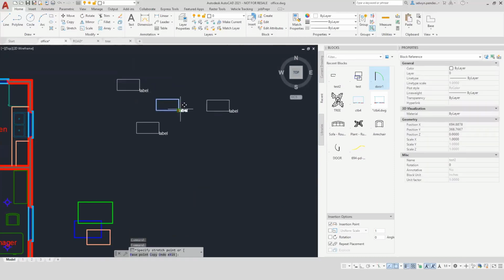We should be able to just use mid-center, position the text. If you're going above the line, do it at bottom center, top center, middle left, or whatever, just so it doesn't overlap the block when you change the scaling. So that's basic blocks with text and annotation, the ability to scale your blocks.